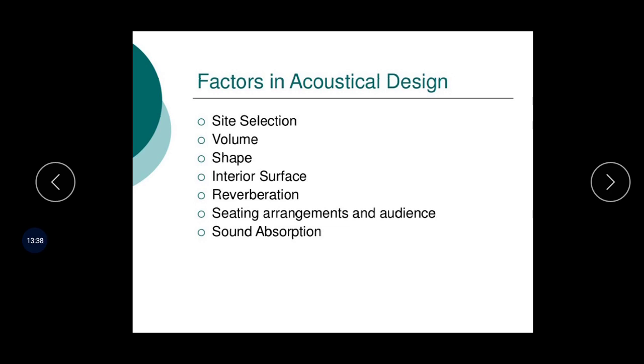To avoid sound focus due to a curved ceiling, the radius of curvature of the ceiling should be made at least twice the height of the room, or less than half the ceiling height, whichever it may be. Many other arrangements may be employed to minimize objectionable reflections and thereby increase diffusion. Detailed design diagrams we can see in the further slides provided in this presentation.